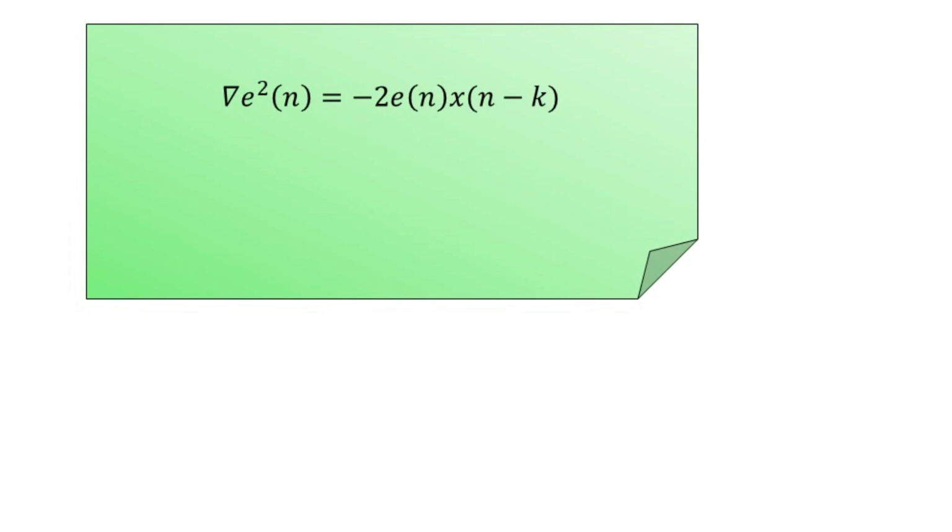Here we denote the variable step size mu suffix n of k greater than mu suffix min, the minimum, whereas it is less than mu suffix max, the maximum, and this is in order to ensure that the VS algorithm, the variable step algorithm, will converge in the mean with only a modest increase in the computation, and the VS algorithm may result in a considerable improvement in the convergence rate here. So this was all about the other LMS based adaptive filters here. The three types we have discussed so far here.